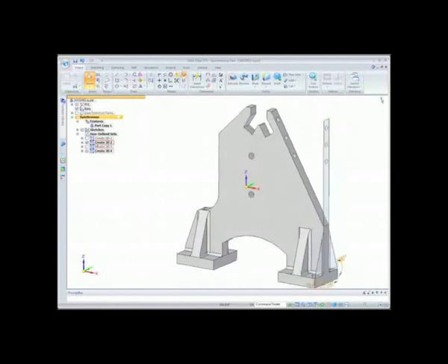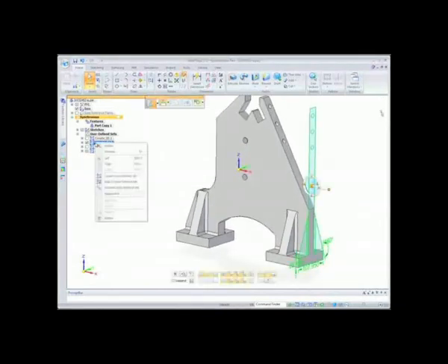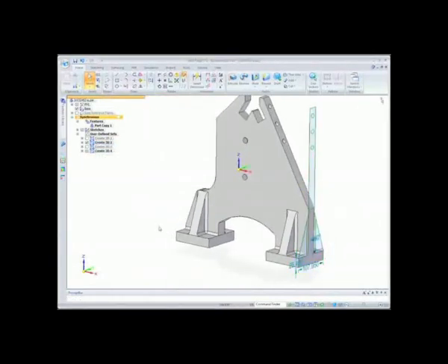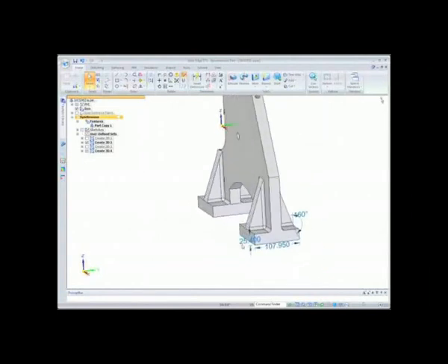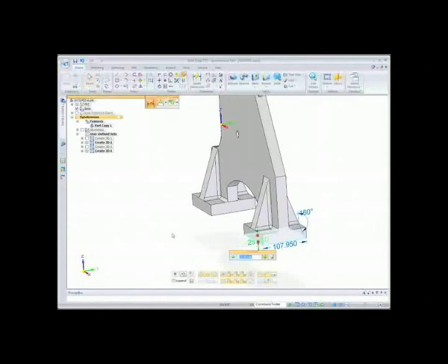And we want to also attach that geometry, or that PMI, to the geometry. Again, if I modify this dimension, if I make this taller, you can see that design intent is being maintained, that both sides are adjusting based on a live rule that says that those two are symmetric or coplanar.